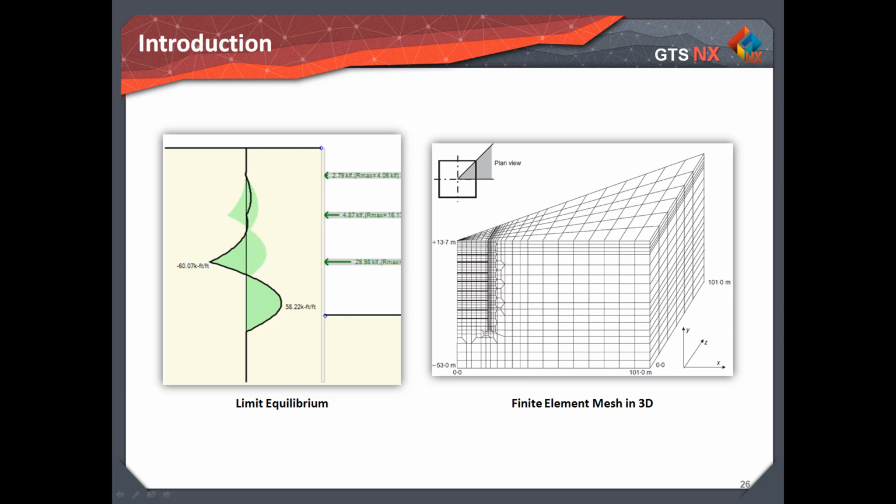Until recent years, the analysis of retaining structures has been done by simplified methods such as Rankine and Coulomb methods or traditional limit equilibrium methods, which are based on conditions at collapse when the full strength of the soil is mobilized. Limit equilibrium calculations do not in themselves give any indication of wall movement, although some computer software considers the interaction between the wall and the soil to provide some suggestion of wall deflection. Most of these methods simplify the 3D problem to a 2D problem.